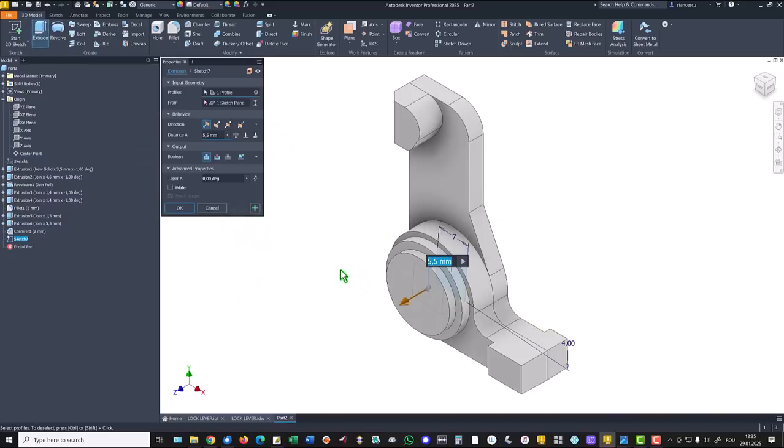Inventor found the only close contour, and we select the other face all the way with cut, and placing here 1 degree, not minus 1 degree, plus the same area is selected and also 1 degree. Okay.